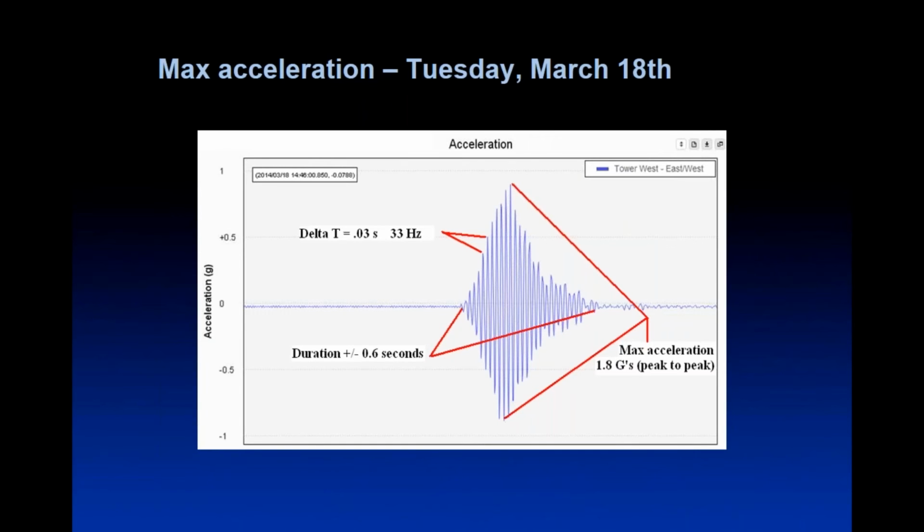Most of those red dots are taken from laboratory experiments. There's only been ever one full-scale experiment on site, this one here, and that lines up fairly well with what's going on in laboratories. So what that says is that we know what human perception of vibration is going to be. We generally design for 1 percentile so that people will not, under normal circumstances, experience vibrations that they don't like. I'm going to press on through here fairly quickly because we're running a little bit short on time.